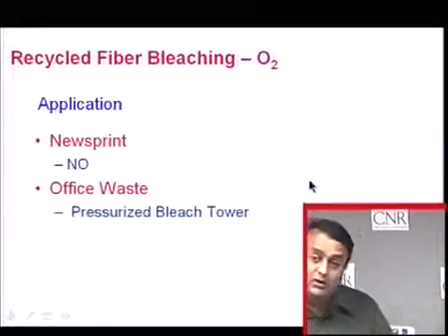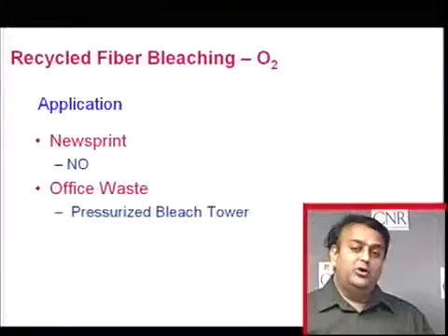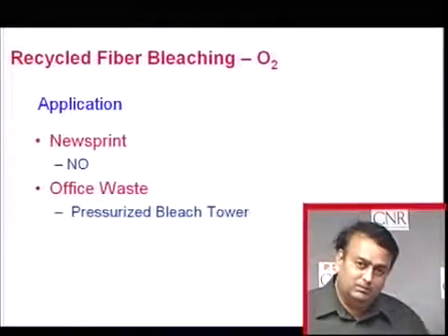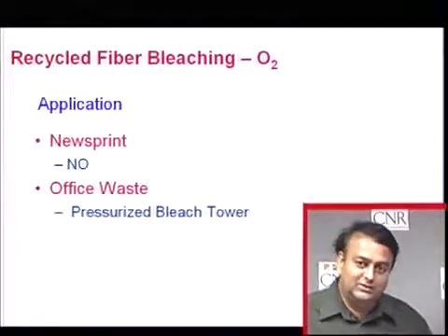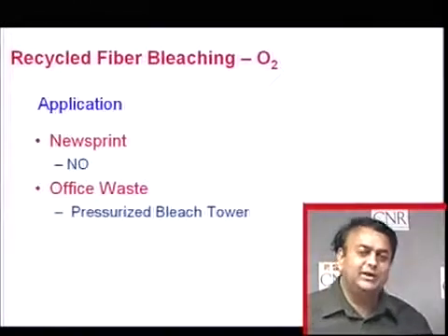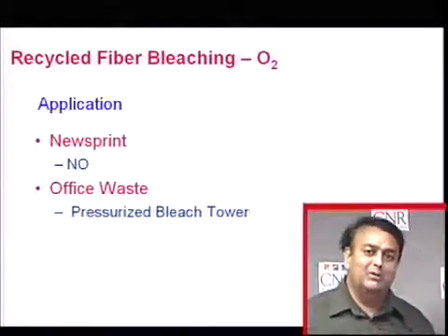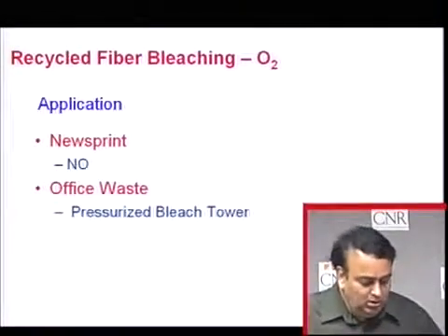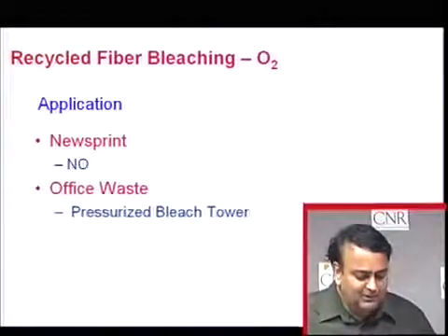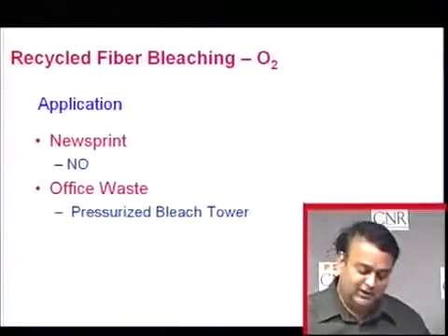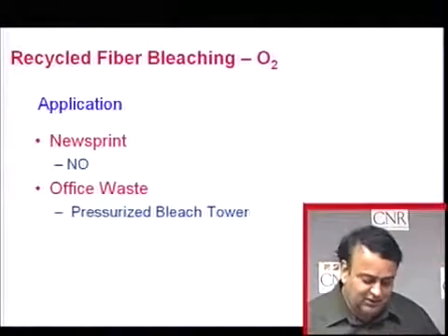Where do you apply oxygen? You don't put oxygen for newsprint recycling because it's going to yellow the fiber. There is a high amount of lignin present. Oxygen is a good delignification chemical, but with such a high kappa number on the newsprint, you may bleed the lignin, you may make the fiber yellow. So what you need is a pressurized bleach tower for office waste. That's where oxygen is going, like shown in the previous diagram.